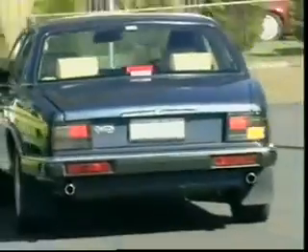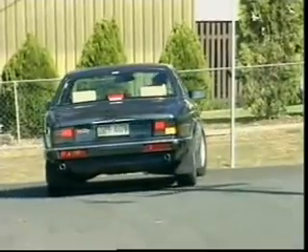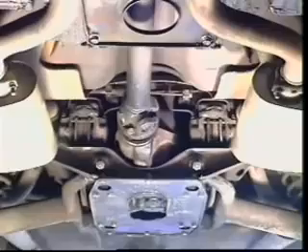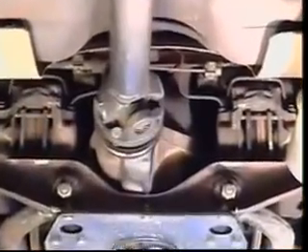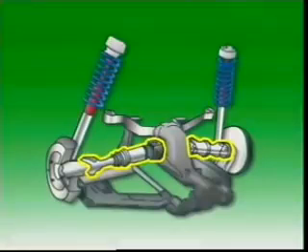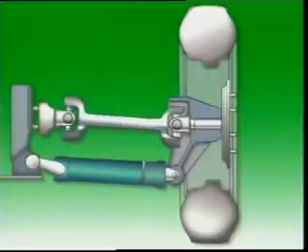On rear-wheel drive vehicles, the suspension arrangement has to allow for the external drive shafts to transfer the drive to the wheels. The final drive assembly is normally fixed to a crossmember, and since it must absorb the torque reaction, it must be secure. Drive shafts, either with conventional or constant velocity joints, transmit the drive to the wheels. When conventional universal joints are used, each drive shaft may have a spline section to accommodate changes in shaft length due to changes in wheel camber with suspension action.